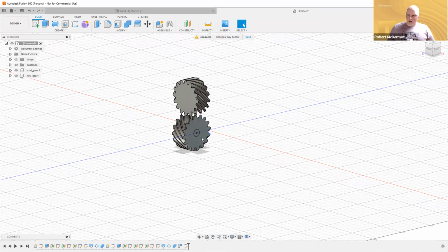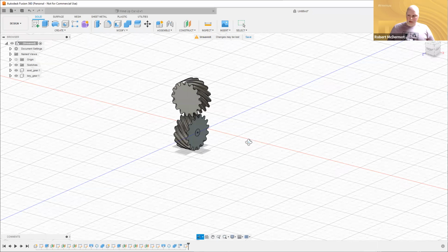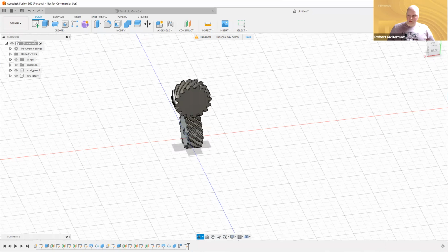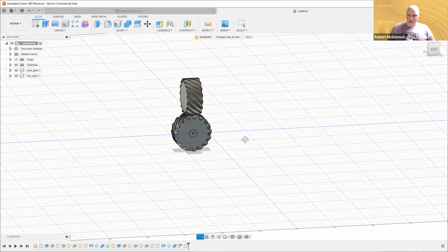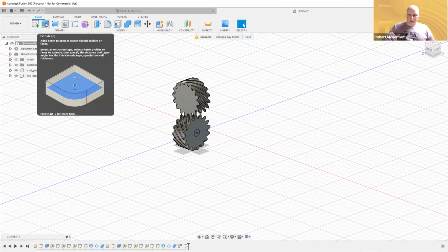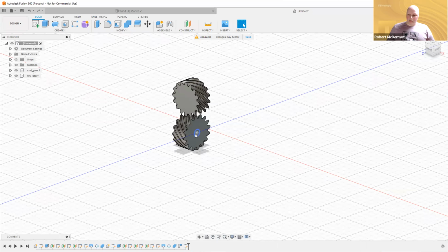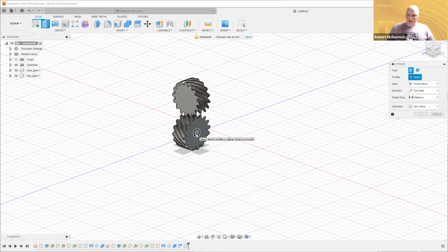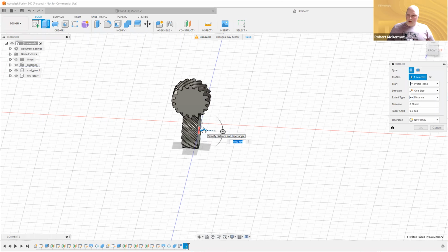And now I have a circle on this face. It doesn't do anything. It's flat. It's not really part of the model, but it's there for me to make some 3D geometry from, right? So one of the ways to do that is to use the extrude tool here. You take a sketch profile, they're called, which is this circle, and you can extrude out. And so I'm going to hit that. I'm going to select the circle. It presents me this arrow, right? And I can drag this arrow out, and now I have a cylinder from my circle.